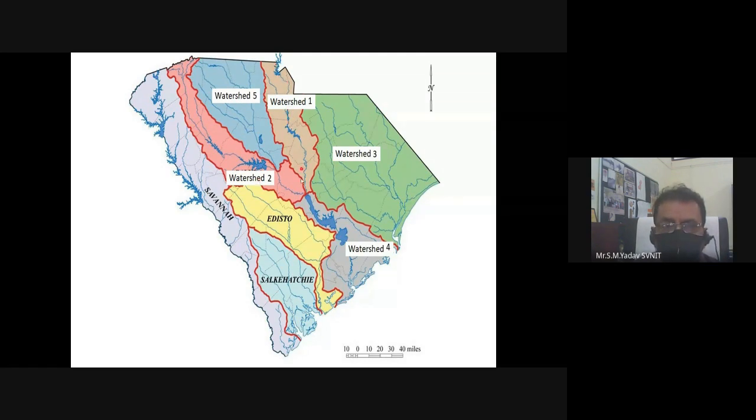You see that watershed 1 is having this stream, watershed 5 is having a number of streams, drainage density is more, and it may be confluencing with it. In watershed 2, there is a kind of reservoir. You can see here the water is stored and it will continue here. Watershed 4 has tributaries and some dam is also there. You can see 1 or 2 water bodies there. So water bodies are more for watershed number 4, and watershed number 3 is near this particular stream, which is flowing in watershed 1 and watershed 4. So when there is a flood, the water may spread into watershed number 3.